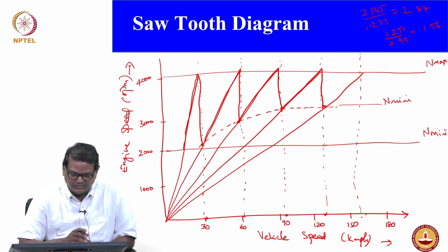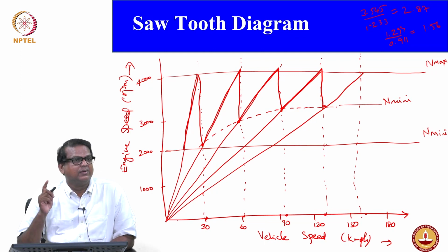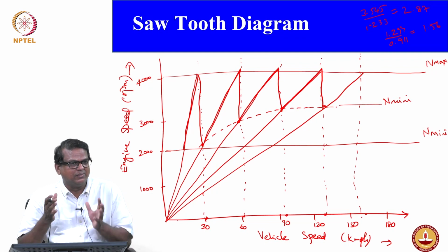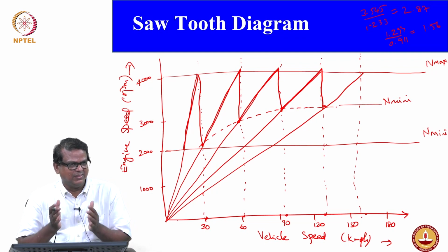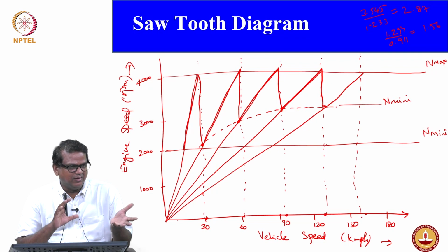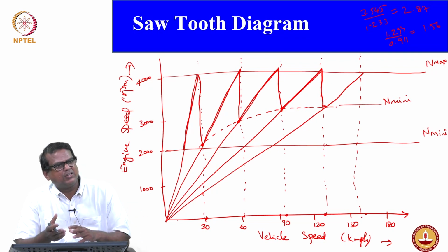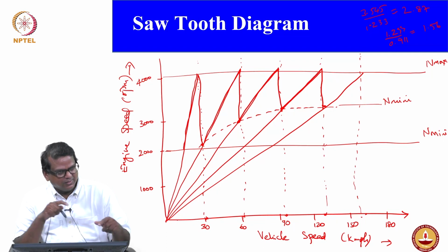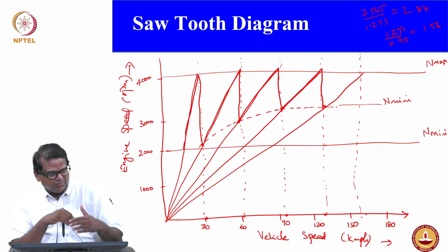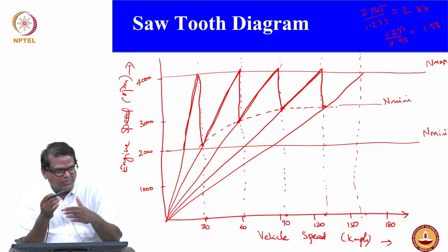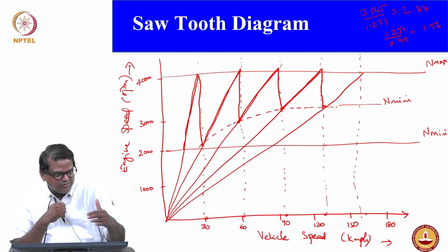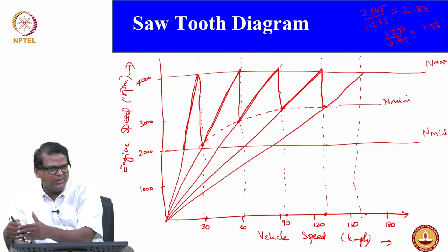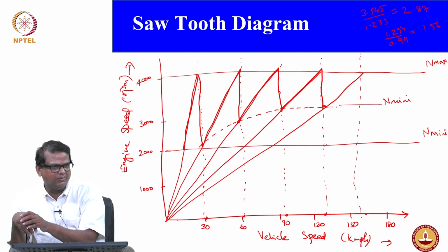for the Maruti Dzire gearbox using progressive or logarithmic gears. It's not the geometric progression, but we are using logarithmic progression. That's the reason the step ratio changes. As step ratio changes, the gap between maximum speed and minimum speed keeps reducing. By doing that, you can save your fuel.